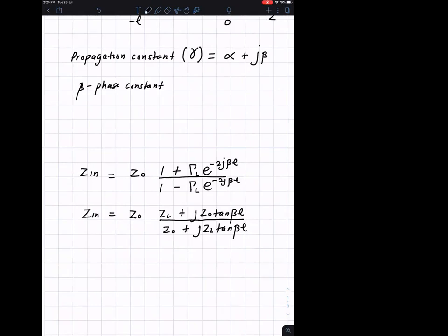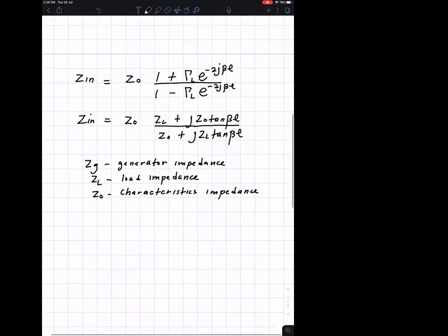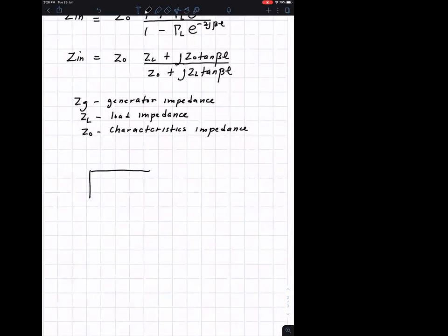If your piece of wire happens to be a transmission line. Characteristic impedance, you know, right? Last time, remember, you guys went to the microwave lab, and you saw the network analyzer, and it was written here 50 ohms. Okay, that means since this equipment is a 50 ohm equipment, therefore you need to connect a cable that also has a characteristic impedance of 50 ohms.